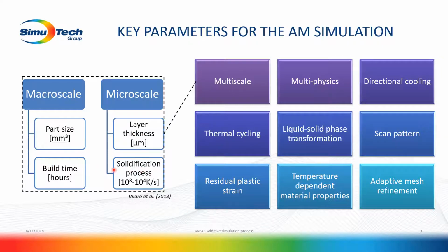And this is the same thing in terms of time. Printing a part can take up to hours or some days or even one week, but knowing that when the laser is melting the powder, the solidification process can take 1,000 or 10,000 Kelvin per second, just again imagine what would be the time step required to capture the solidification process, and knowing that a build can take up to several hours or days, it will lead to an infinite number of time steps.